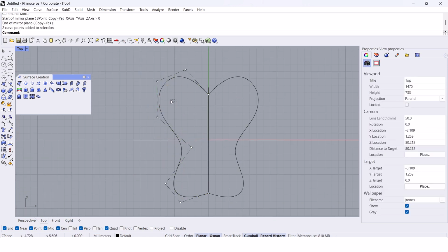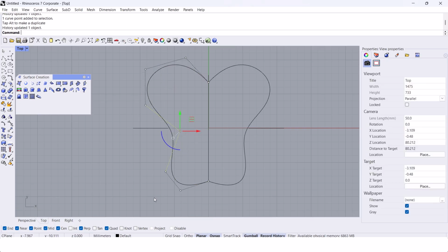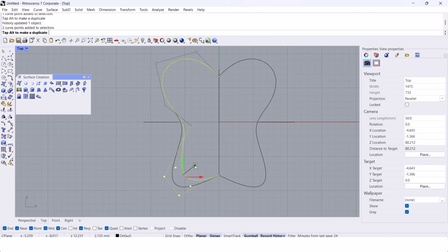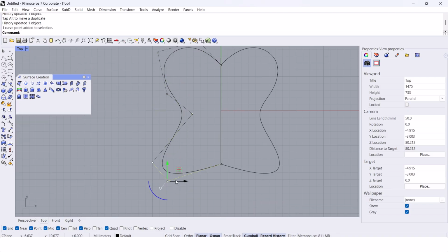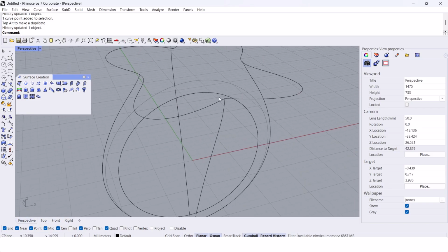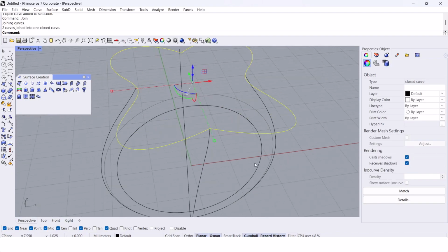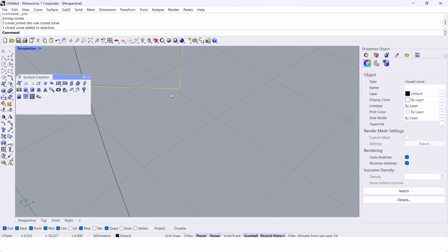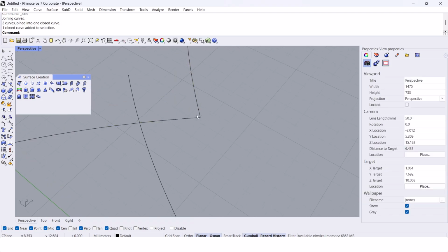Mirror. History is on, so I can change the shape. Don't complain about the shape, I'm just trying to show you how it works. So, as I said, we need a degree 3 curve. Every degree 3 curve doesn't have an edge, or, for example, a kink or a point. So we need to solve this one as well.